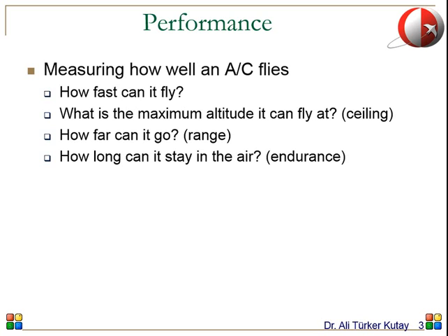Another thing which is related to range but not really the same thing is the endurance. This is defined as the amount of time an aircraft can stay in the air. For certain things, you care more about endurance. For example, for search and rescue missions, you want to be able to stay as long as possible. If you are looking for somebody from the air, you want to be able to stay there as long as you can. You want long endurance there. You don't care about going a long distance, but you want to stay in the air for a long amount of time.